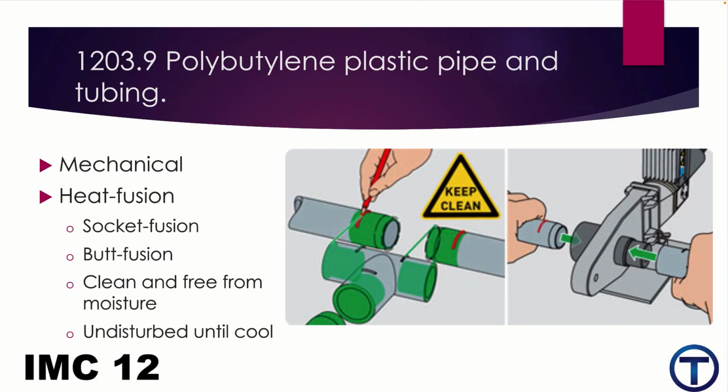In any case, when you're doing fusion to put pipes together, you have to make sure they are clean and free from moisture, and you need to leave them undisturbed until that plastic has fully cooled.